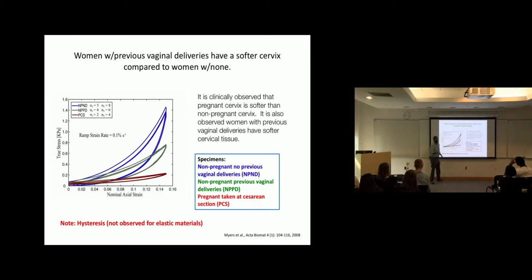There's dissipation. First thing to notice. Clearly, there will be dissipation in viscoelasticity. Why? When you break a crosslink, there is energy stored in that crosslink. You're breaking it. Where does that energy go? As heat. That energy is dissipated to the fluid surrounding it. So there will be loss. So when you take the stress strain curve, there will be hysteresis or energy loss. The area under this is the energy lost.